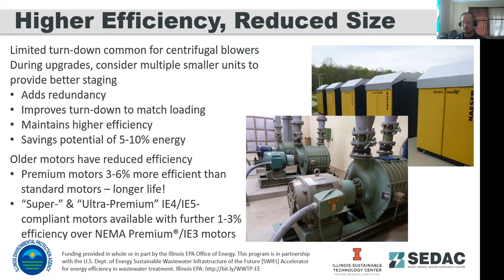While that does provide some energy savings through reduction of mass flow through that blower, it's not as efficient as putting a VFD on that system and slowing them down. Again, the consideration there is you can only slow down so much and still maintain your distribution pressure requirements and your heat dissipation requirements for those motors.